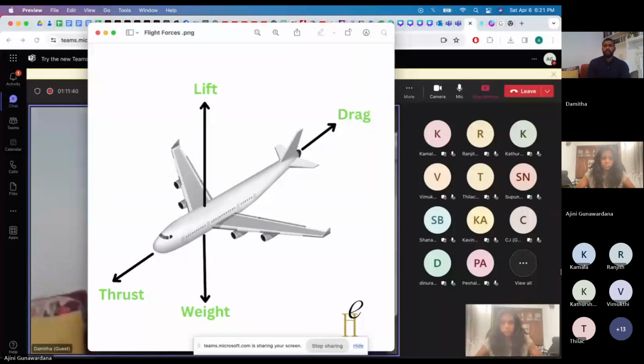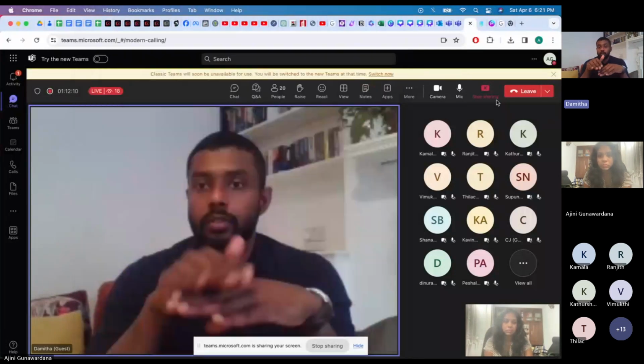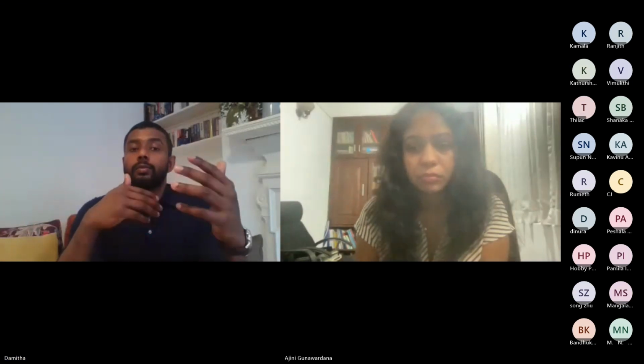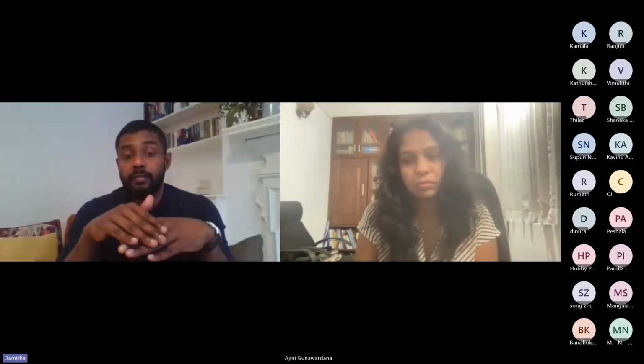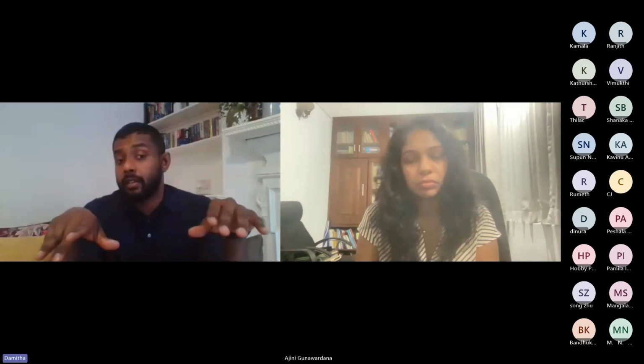For example, most aircraft structures are made from aluminium, and very modern aircraft like the A350 and 787 have moved to a 70-80% composite design. The composite could be carbon fiber composite or fiberglass composite. A composite is where you have a matrix, with resin layers and fiber layers working together to create the required structure. It's done through the orientation of these layers, to meet the requirements. If it's a linear load, it's made in a different way. If it's a shear load we are trying to overcome, it's made in a different way.